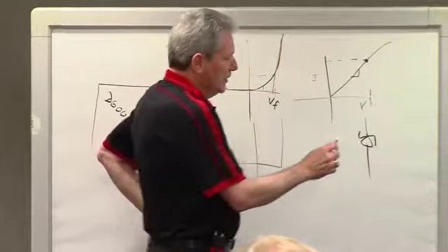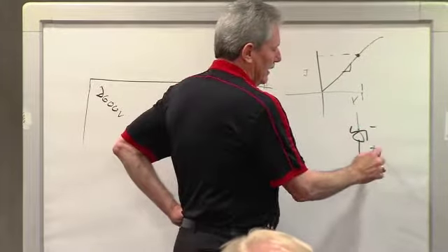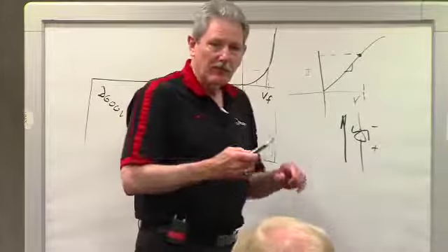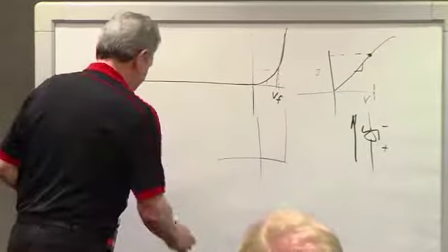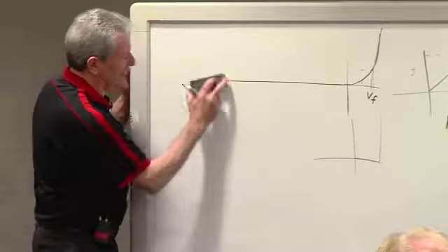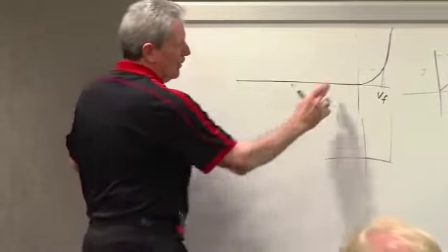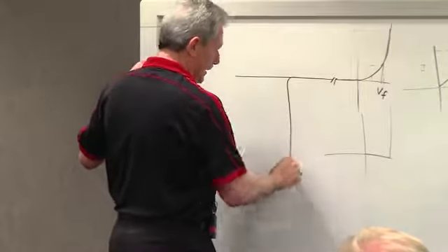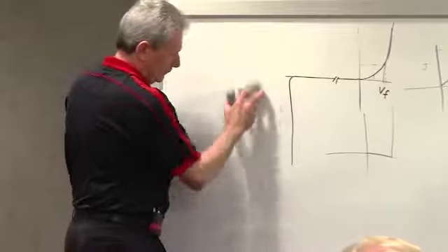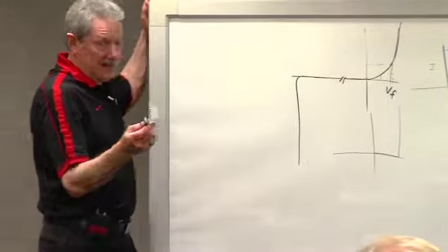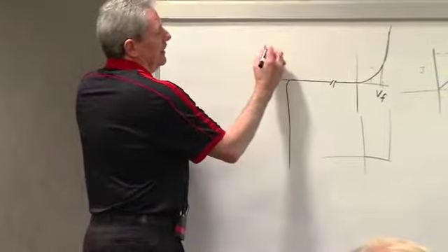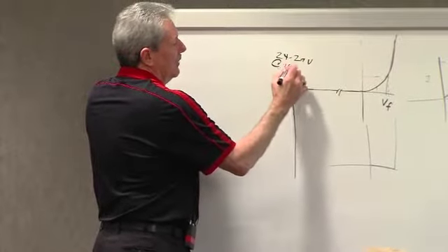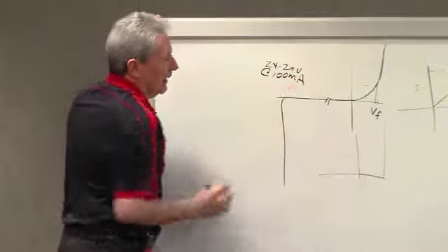schematically. You still have the cathode and the anode. The current flows in this direction, but when the reverse voltage gets to a much lower level, let's put a back here, it turns on. This, for our diodes, is 24 to 29 volts at 100 milliamps.